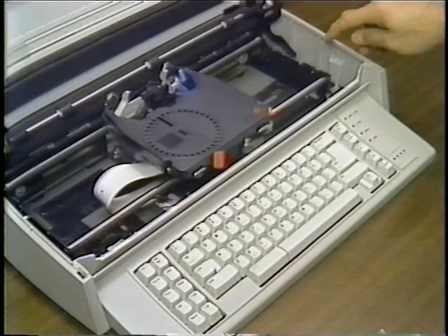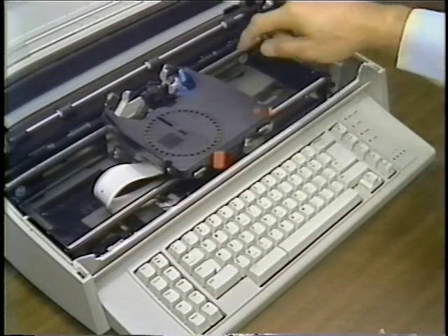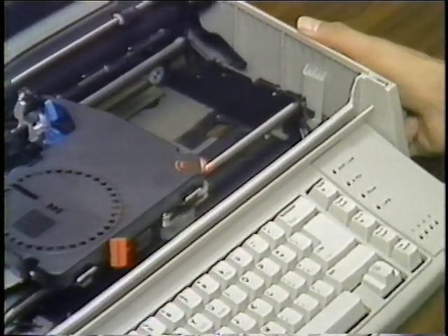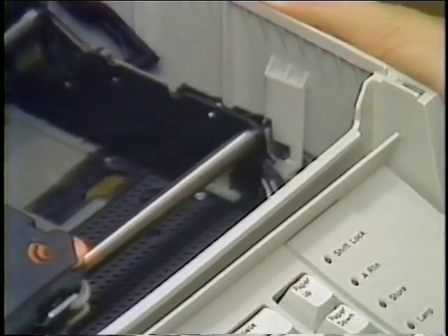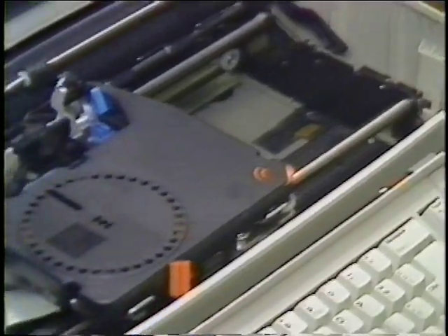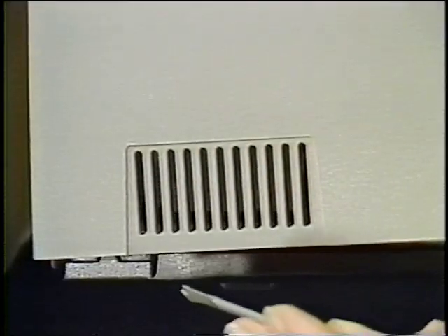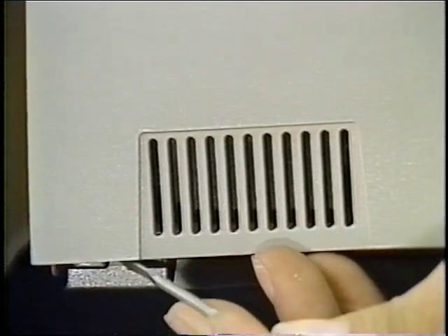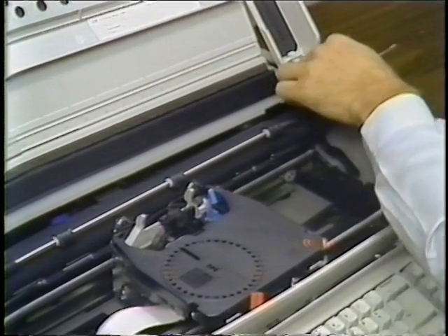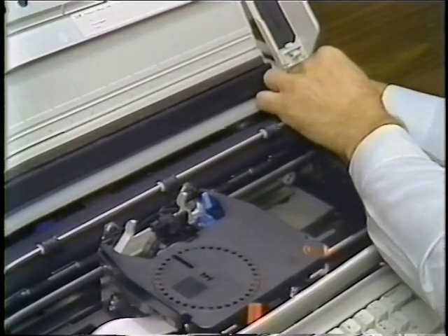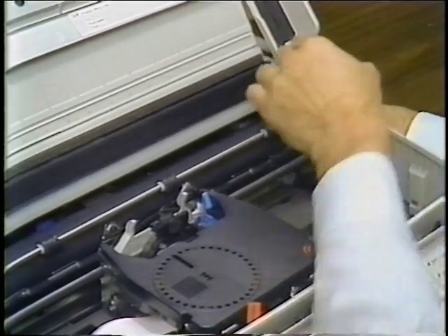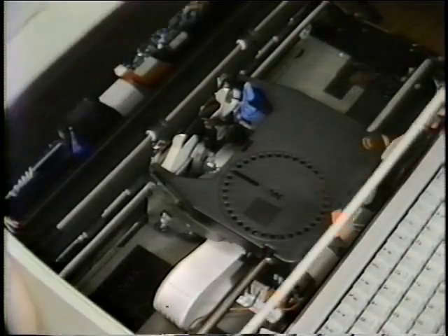Locate the two front cover latches. Reach under the sides of the machine and push the latches in until they release. Locate the left rear latch and use a screwdriver or the pusher end of a spring hook to push the latch in until it unlatches. Locate the right rear latch and unlatch it the same as the left cover latch. Lift the cover off the machine.